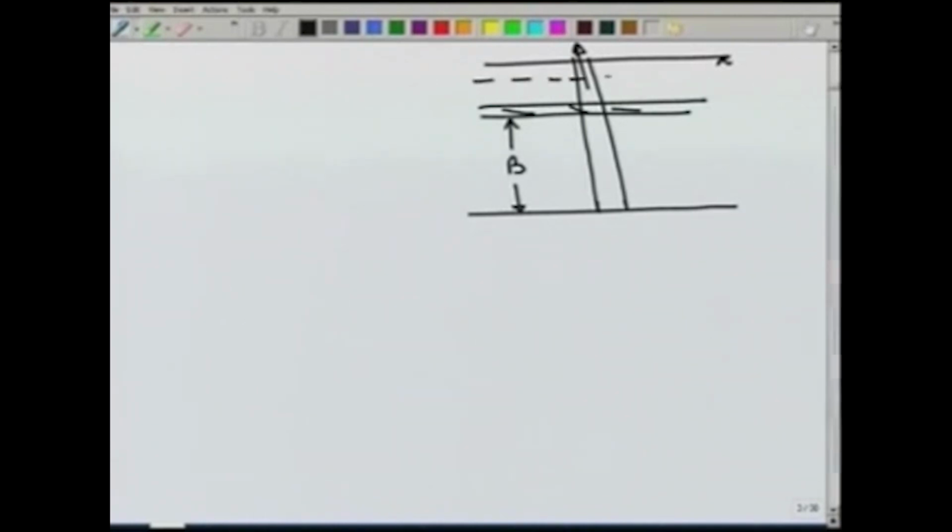Initially, we have a horizontal piezometric head level as capital H. The pumping rate Q is assumed to be constant. So, we are pumping the aquifer at a constant rate, and then we also assume that we have reached steady state conditions. So, the drawdown is not changing with time, that is the cone of depression remains constant with time.